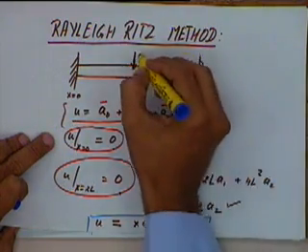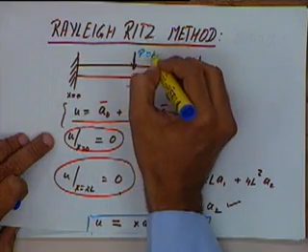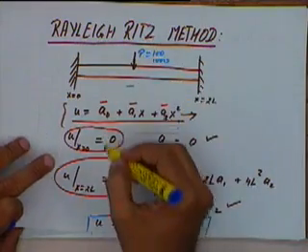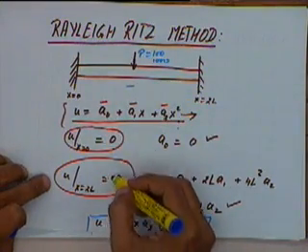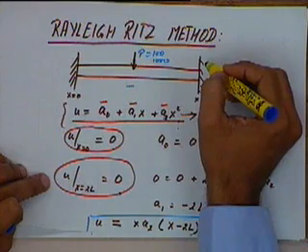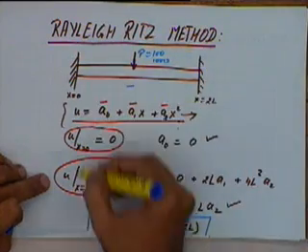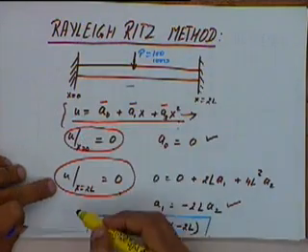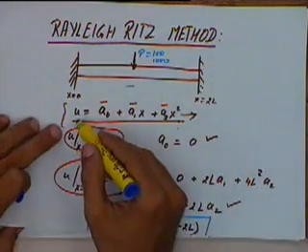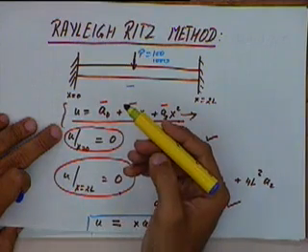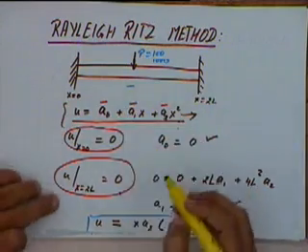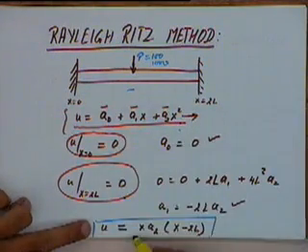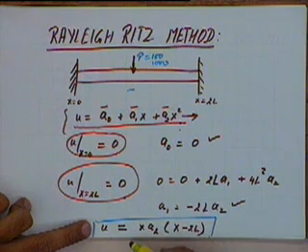Even if I apply a load P equal to 100 newtons, or a load P equal to 1000 newtons, these boundary conditions are going to remain the same, but the deformation will not be the same. So obviously, if you are doing it correctly, just by applying the boundary conditions you should not be able to solve the u vector. It doesn't make sense. By applying the boundary conditions, we will be able to simplify this expression, but we will normally not be able to solve it completely.